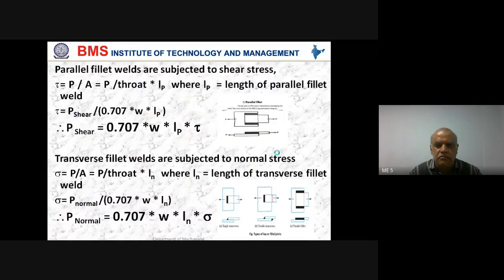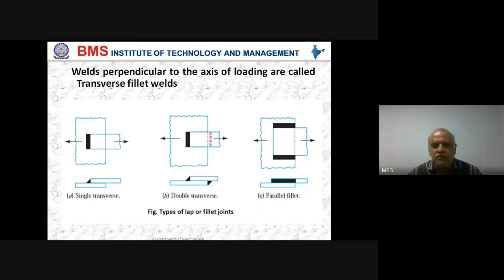Whereas when you go back to parallel fillet weld over here, you will have 1 free end, another free end, third and fourth. So I is equal to 4. So the number of free ends will be 4. The effective length will be summed up with 5 times 4 ends, that is effective length plus 5 fours are 20 mm will be added to the total length of the weld.